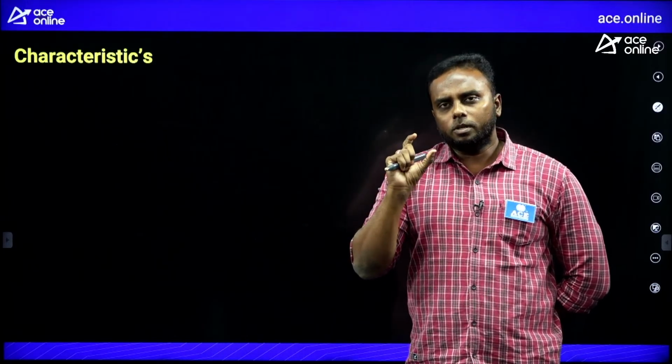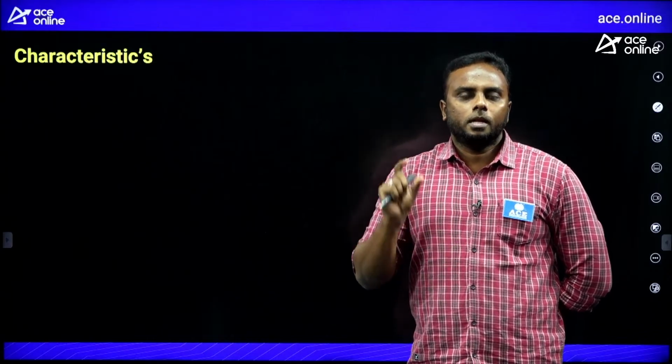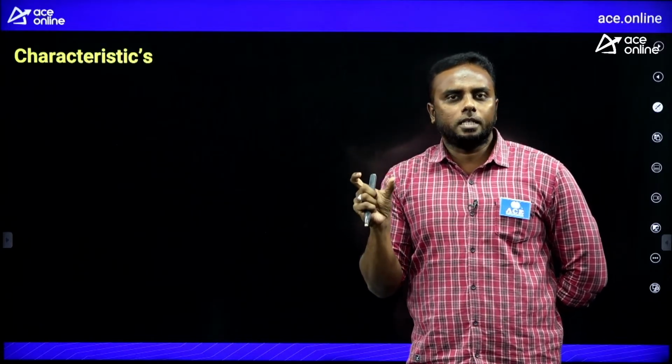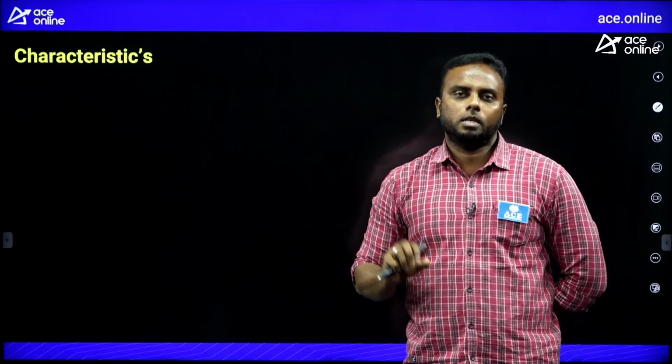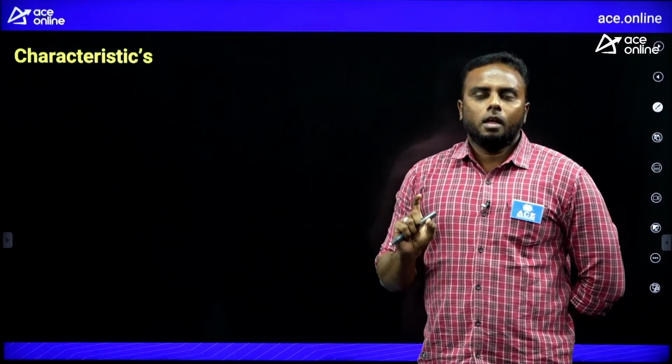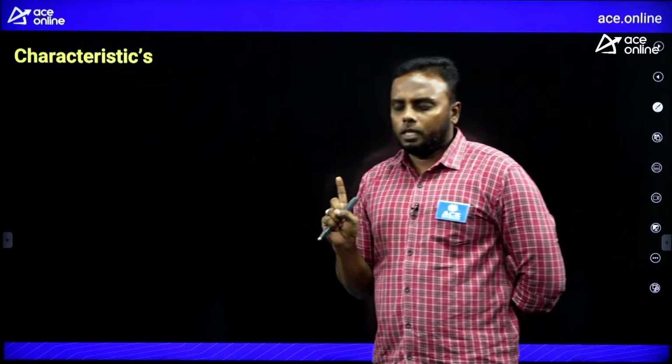But what is the shape of series motor? Important ikkada. Series motor lo shape of speed torque characteristics is what? Rectangular hyperbola. No load, dangerous high speed, and whenever load increases, speed of the motor quickly decreases. Rectangular hyperbola shape. And what is the speed in a series motor?